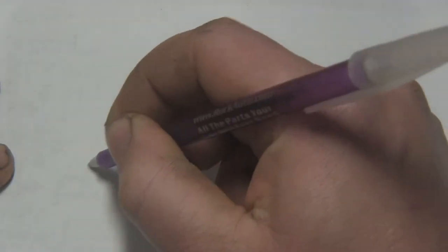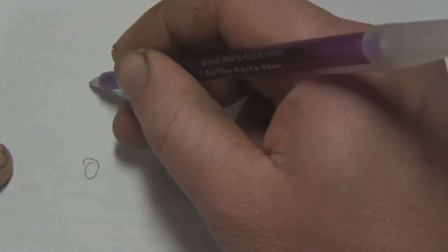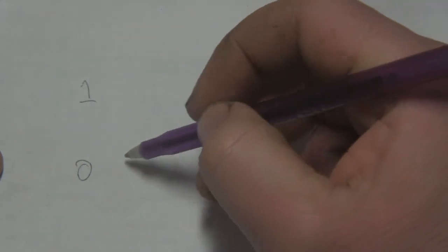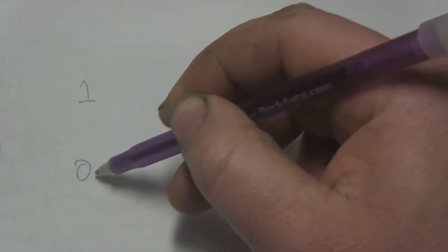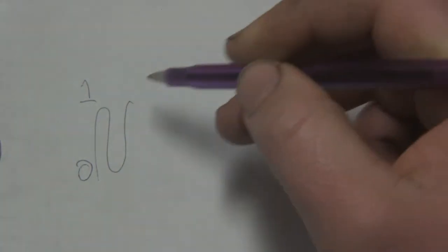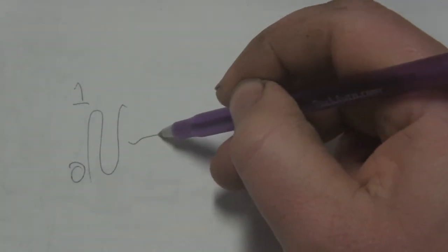Let me draw it on this paper here. So let's say this is your 0 to 1 volt, and this is the downstream oxygen sensor. The upstream switching up and down, right? The upstream's doing this. What you want to see the downstream doing is kind of hovering.